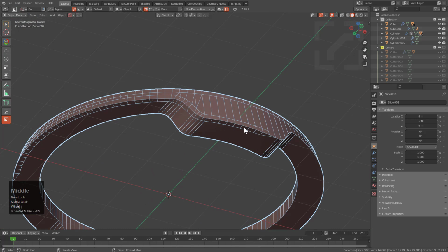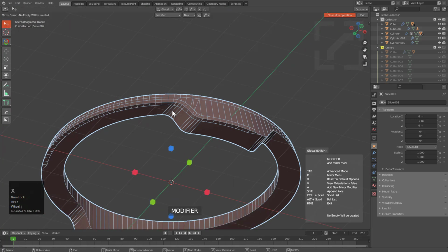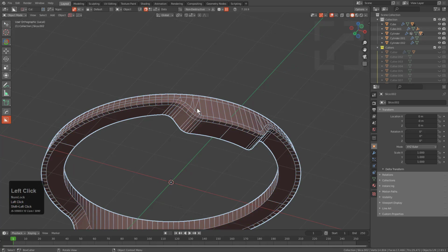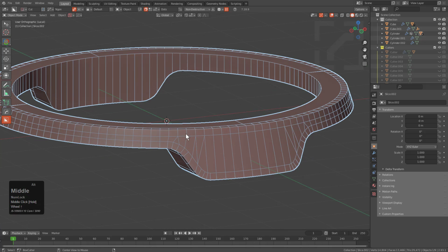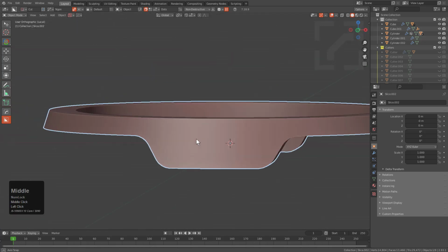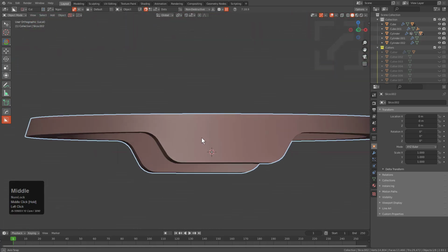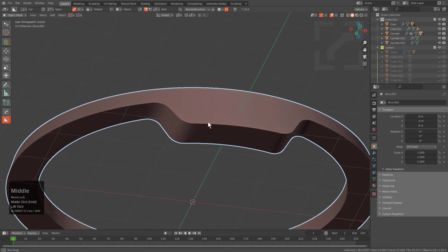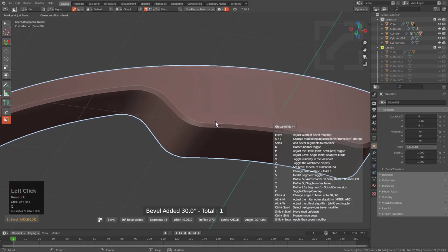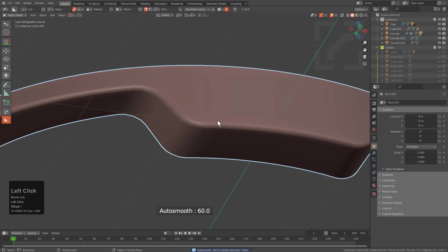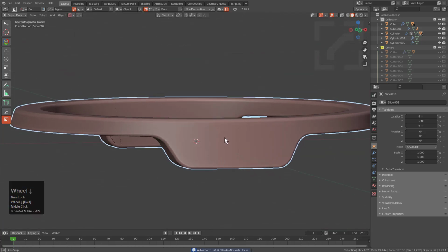So you might have also noticed that I did this partially. That's because I could press Alt X, scroll to something like symmetry, shift click on X to keep mirror, and then click on Y to do Y and be done with Y. So if we press Alt V and we get out of our wireframe, we see that it looks like we did nothing at all. However, now we can control click bevel and we can just really add a bevel there and the surface will hold together.